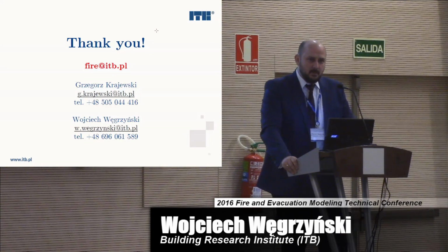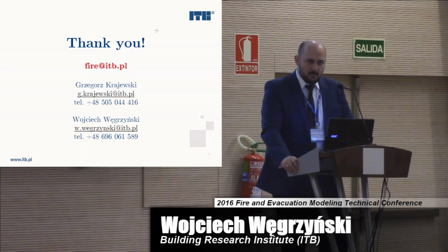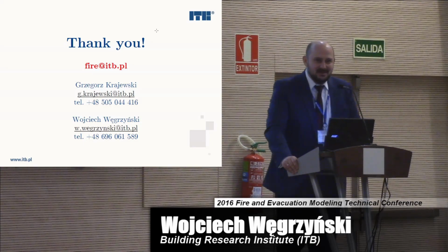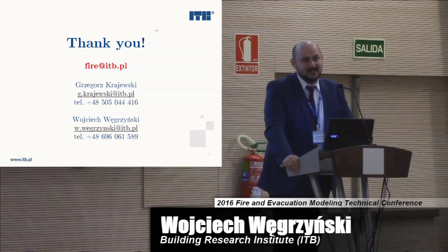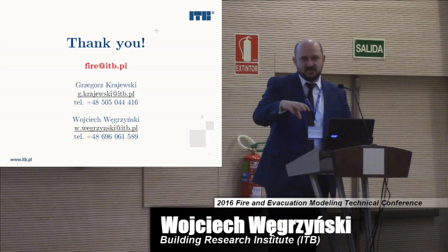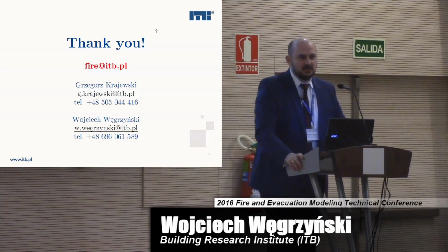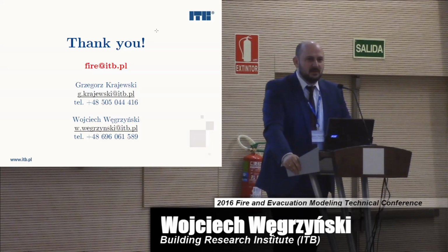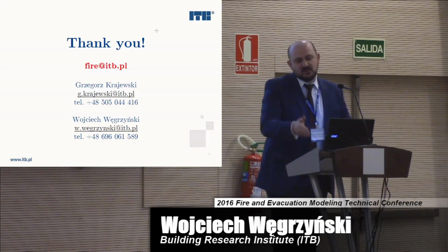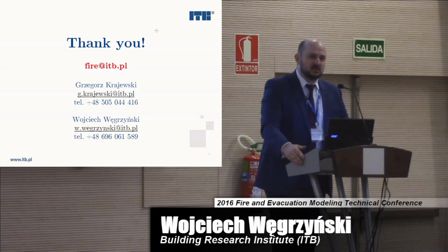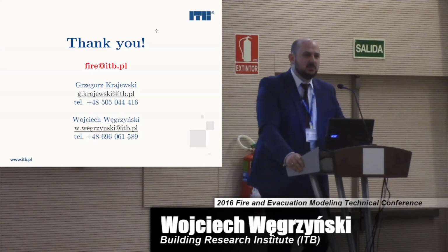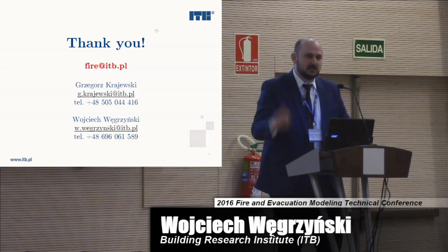Okay, so you introduced in the same model wind simulation and fire simulation. Yeah. It makes a huge volume. Tell me about it. Yes, it does. And that's the reason why you wouldn't like to have 12 fire simulations with the wind. We just did that once for science, and that's enough. And you need to first find the worst wind and then just follow. But we're not computationally ready yet to just do it like this.